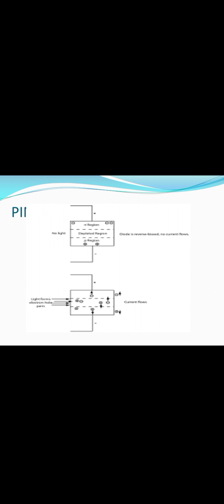Between the P and N layers, electron hole pairs are generated when light is incident on the intrinsic region. The generated carriers are outside the depletion regions. The electron hole pairs then drift into the depletion regions and a delayed displacement current is produced.